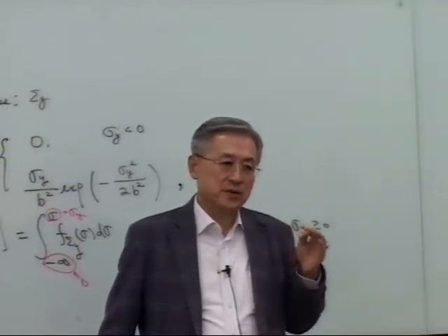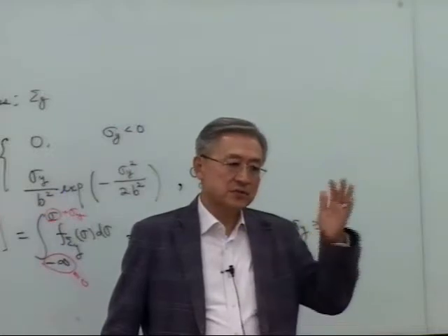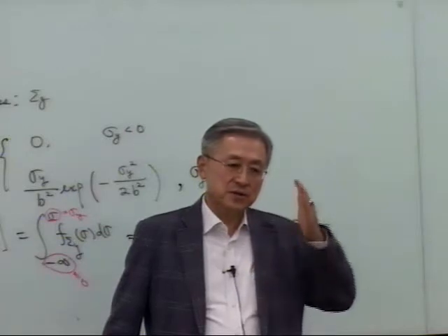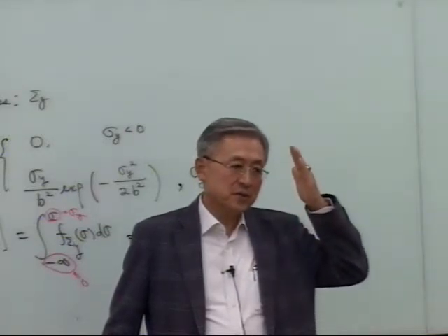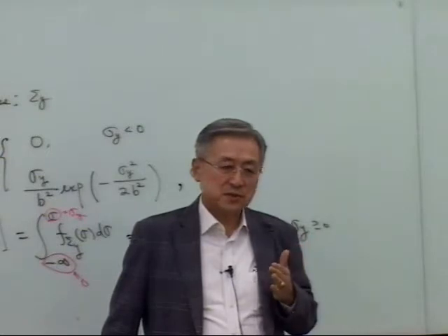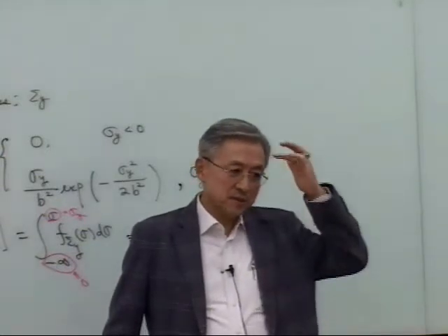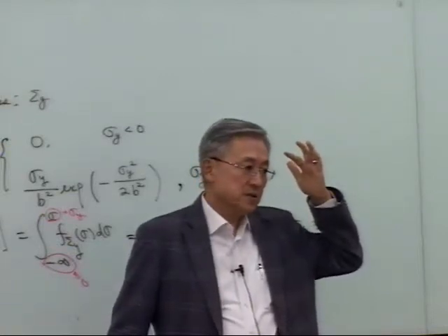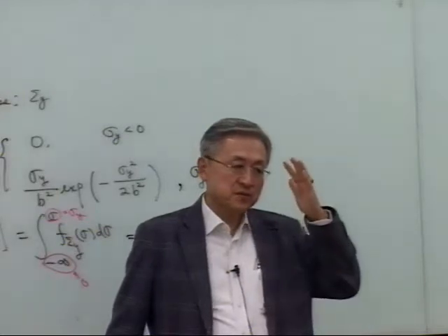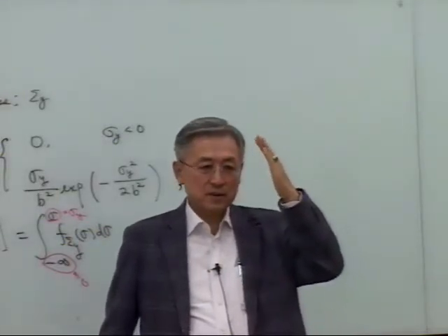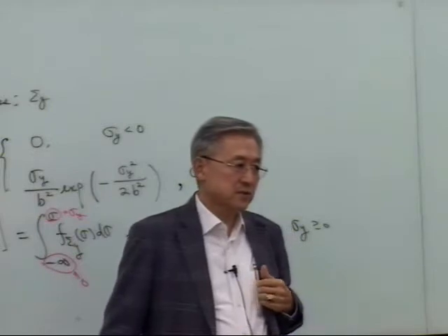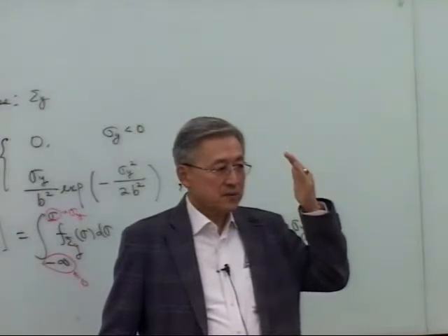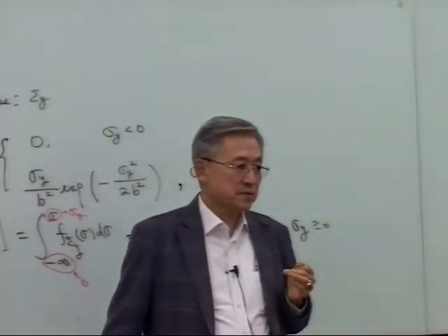Loading and strength generates the surface for the probability density function. Then you know the safety margin is equal to R minus P. You can visualize that, right? That's a safety margin. The safety margin generates the limit state function. Jinggyun, are you paying attention? That generates the so-called G function.